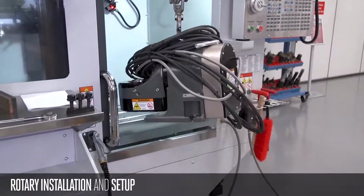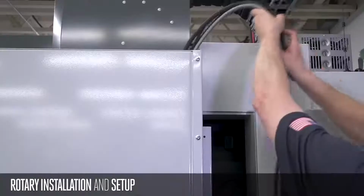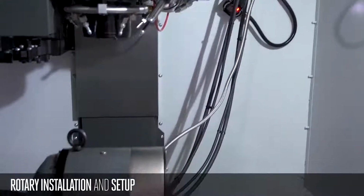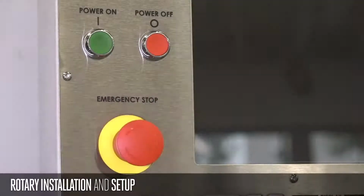So I've got my rotary on the table and I snugged it down. I fed the cables up through the enclosure and made sure that I had a nice drape on the cables when the table was as far away as it's going to get. Now I'm going to shut down the power before I connect the rotary cables and the airline.